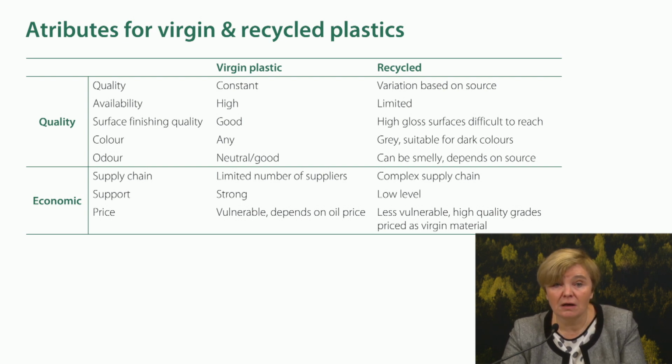Usually, the quality problems coming with the recycled plastics are in smell. So in some cases, you have different smell. It depends what was the source of the recycled plastic. So before purchasing one, probably would be a good choice to test a small batch of it.